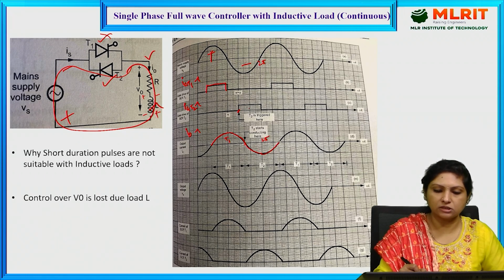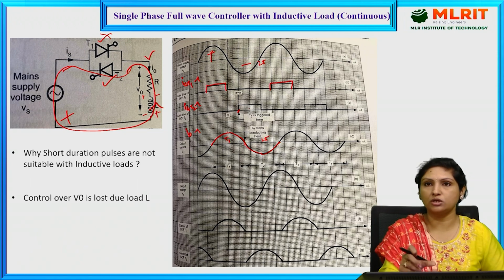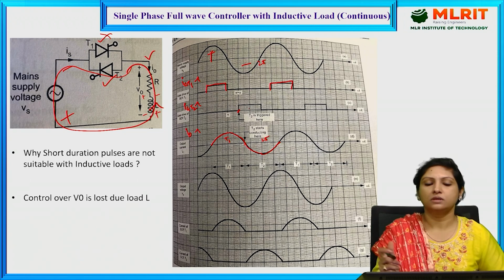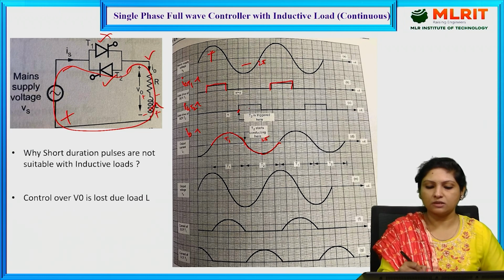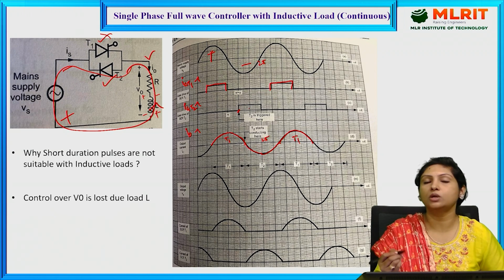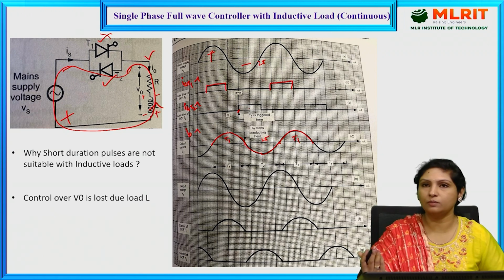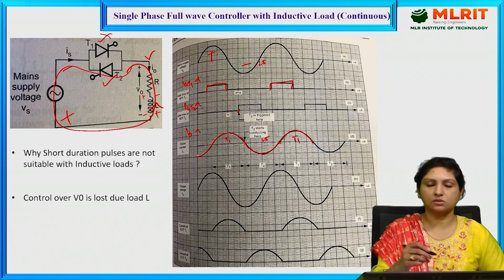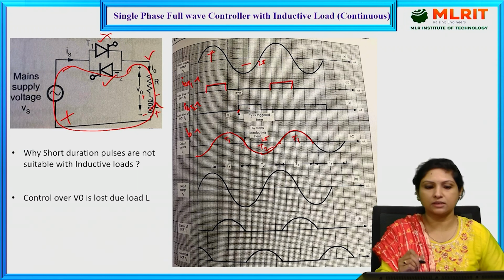The moment it reaches 0, at that instant, again the triggering pulse for thyristor 1 is ready with a long width, such that the moment the current becomes 0, we can provide the triggering pulse for thyristor 1 and it starts conducting current through the load. Thereby, continuity of the current flow will be maintained, which is very much required. So this is all about the output current waveforms, where during the negative half cycle T2 has conducted and during the positive half cycle T1 has conducted.